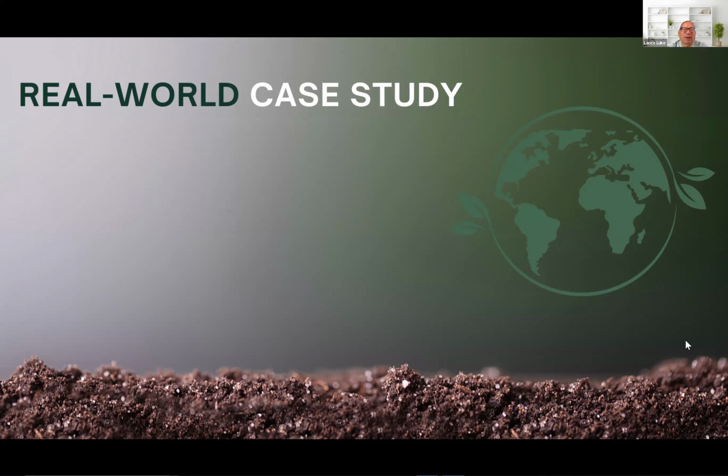So it was determined that something was going on with the soil. We had to do soil investigation and soil studies, where they drilled through the asphalt to get to the soil condition, sent the samples to the lab, and had a soil study done. And it was determined that there was too much moisture in the soil. So the bottom line was that the soil that was backfilled had to come out.